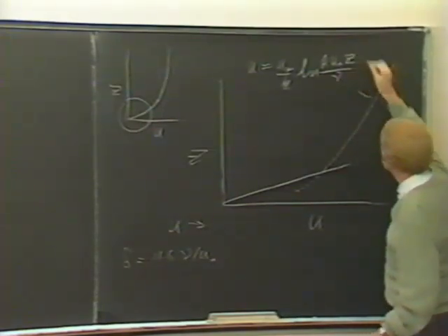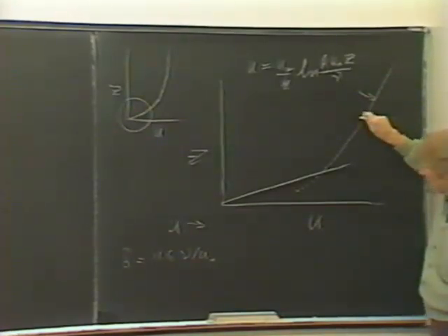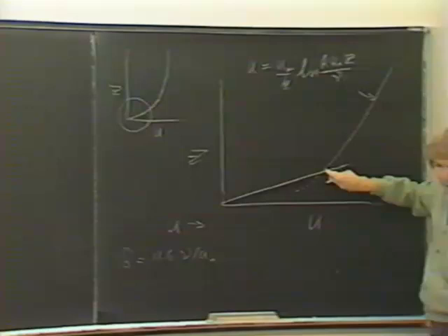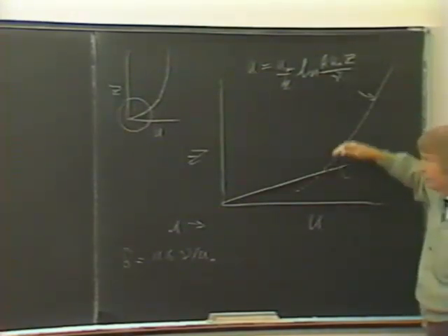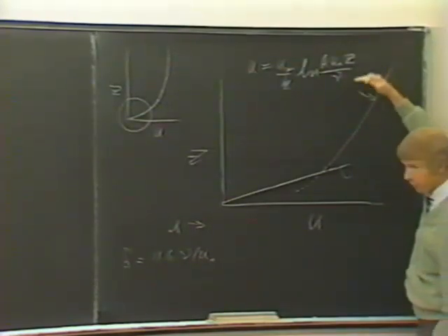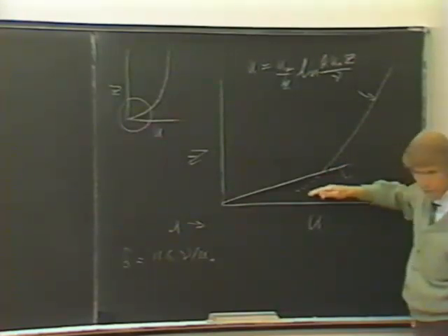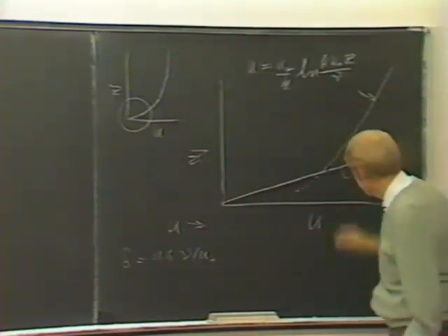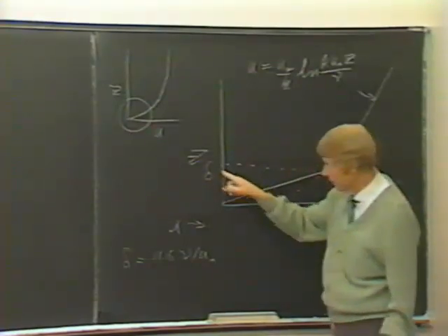In the case of an open channel, that's simply the mass of particles above, say, a square centimeter of bed surface. In the case of the flume, we have a lot of water running around in the rest of it, in the recirculation system. So the change in mass of water per unit area of bed has to include the change in the mass in the return lines and pump as well. So that YE is the effective depth of water, which is simply the volume of water in the flume divided by the area of the bed on which it deposits.